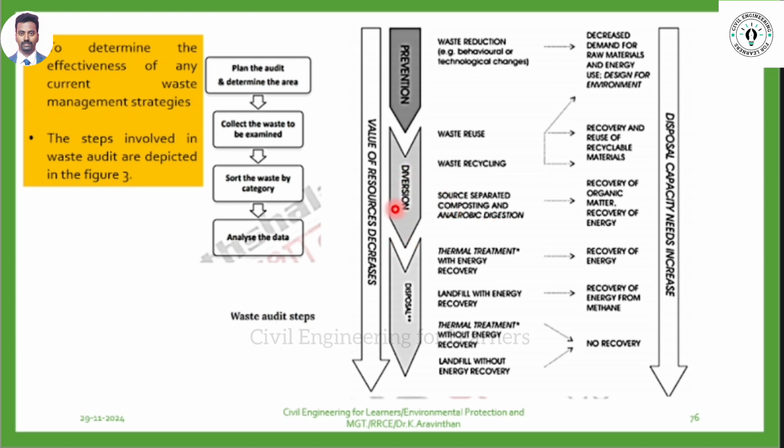From an industry, if more organic wastes are there, you can make an anaerobic chamber. Imagine hotel industries, they can do it. Hotel industries, what type of waste do they produce constantly? Digestible waste, food waste. So for hotels, in your hostel you have kitchens, no? Daily they are going to produce food waste. So they can collect and keep it in a container. What happens? The decomposition will happen. You can get methane gas from that. So this is diversion.